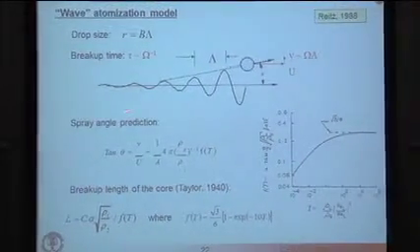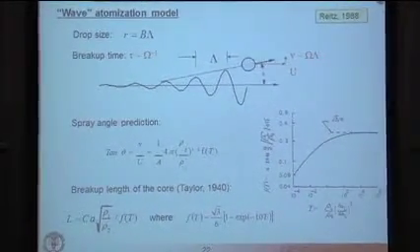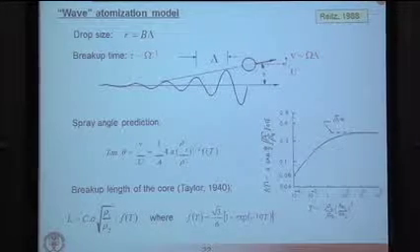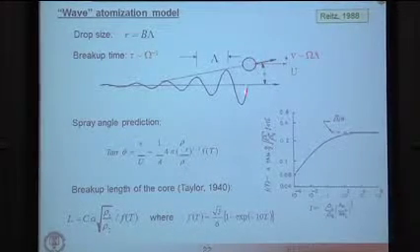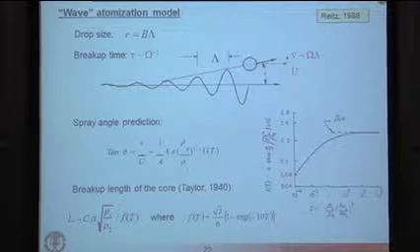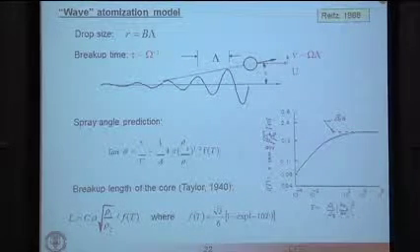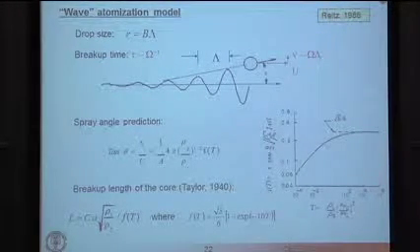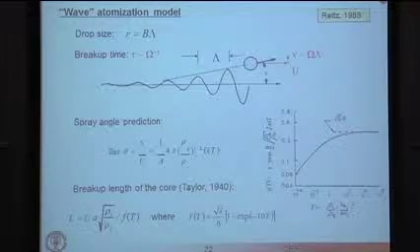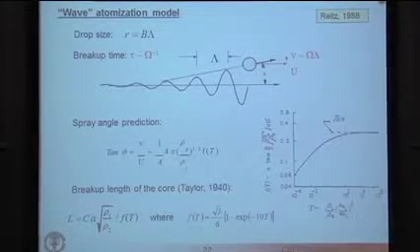We know the axial velocity that we got from our nozzle cavitation model, but now we need to know the radial velocity. And so that's what this spray angle tells you. So that's only for the liquid, yeah. And then my other question was for the breakup length. There seems to be a physical correlation for the breakup length, yet that's an input that you can change and use as a tuning constant. So I'll tell you how we do that in a minute, yeah.